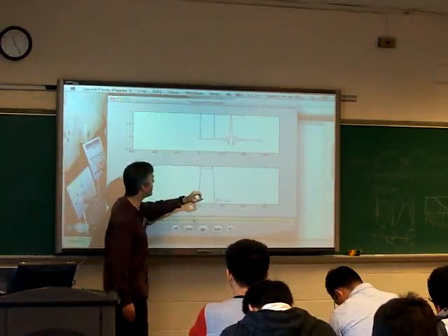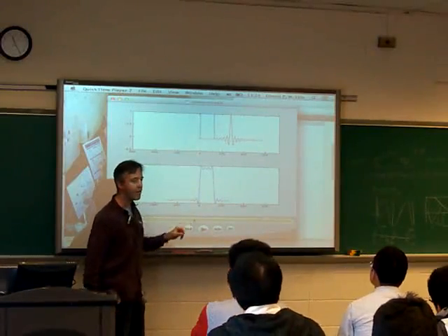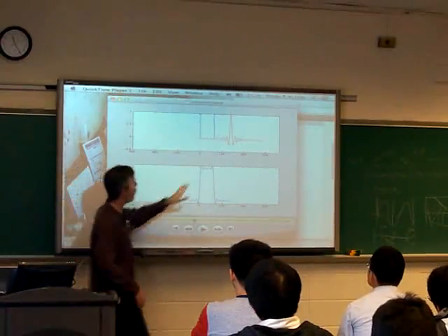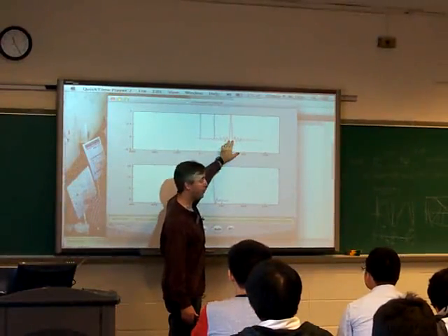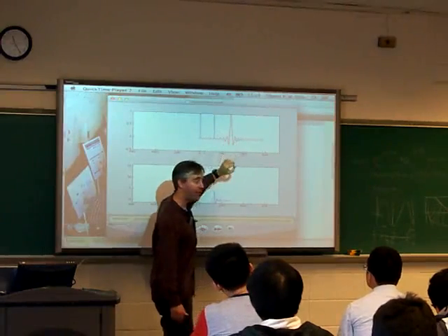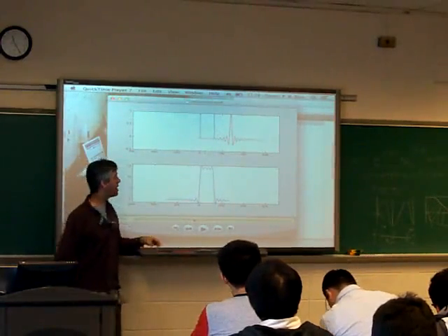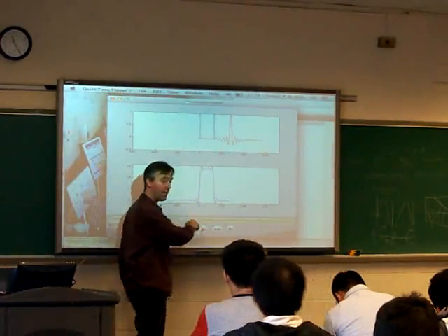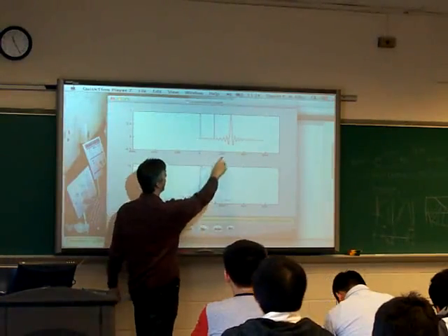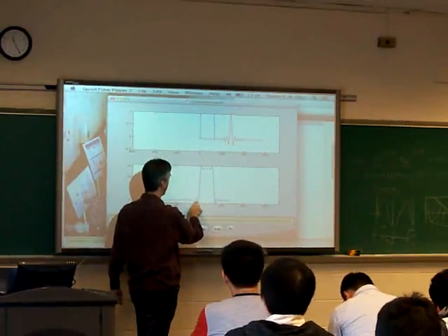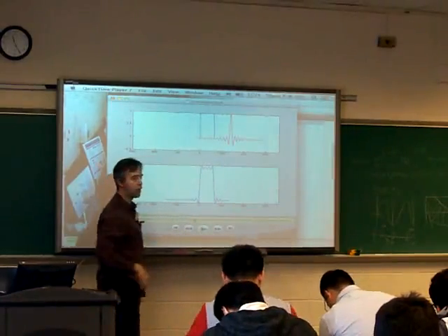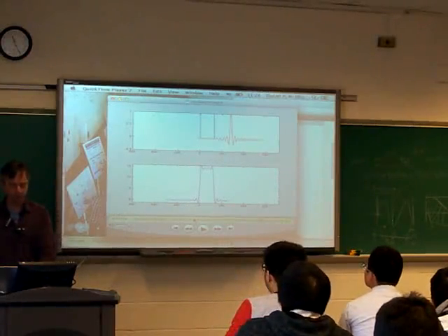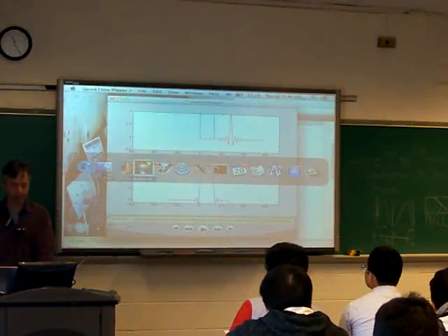And moreover, you can see that the things that are going to really determine these properties are to do with how wide this central lobe is and how large these flanking side lobes are, because the width of the central lobe is how long it takes to get from here to here, the transition width of this frequency response. And then the size of these lobes are the things that give us these large Gibbs ears, these large ringing artifacts around the edge of the transition.